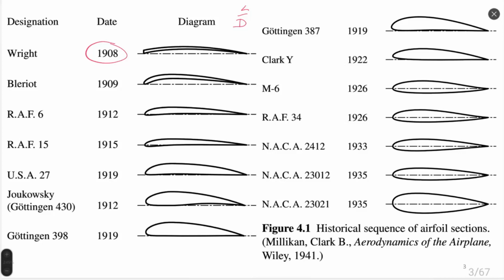Another reason why new airfoils are created is low velocity efficient gliders. Such gliders require airfoils called laminar airfoils. A laminar airfoil has mostly a laminar boundary layer over its surface, and inside a laminar boundary layer you remember that the velocity gradient is significantly smaller than for turbulent flow, so the drag associated with friction is significantly smaller than for conventional airfoils.